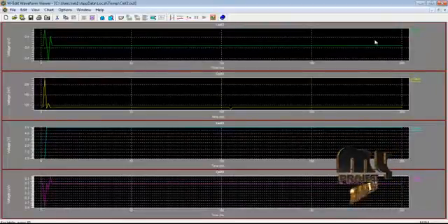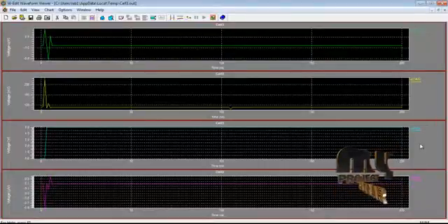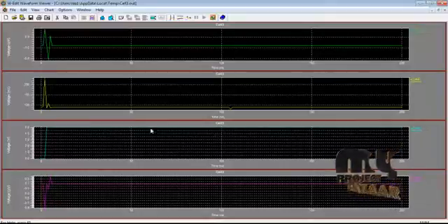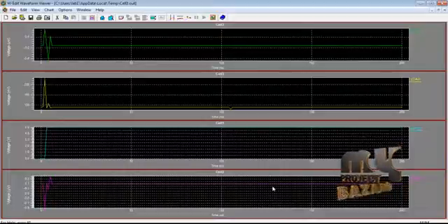This is our row 1 process, this is our row 2 process, this is our row 3, then the row 4. Our SRAM data register matches the match line for only row 3. Then the other signals are at 0. Whichever row is equal, this is an example of the correct output match line direction in the overall simulation window. This is our overall simulation final output result for match line direction. Whichever row is equal, that row is 1, and the other rows are initially 0. This is our overall CAM cell identification process flow.